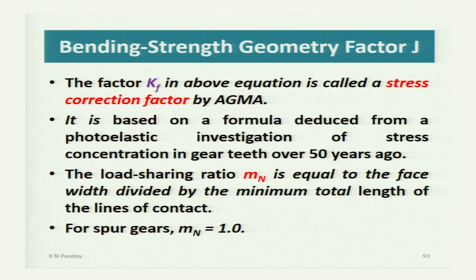The factor Kf in the equation of geometry factor is called the stress concentration factor by AGMA. It is based on a formula deduced from a photoelastic investigation of the stress concentration in gear teeth over 50 years ago.